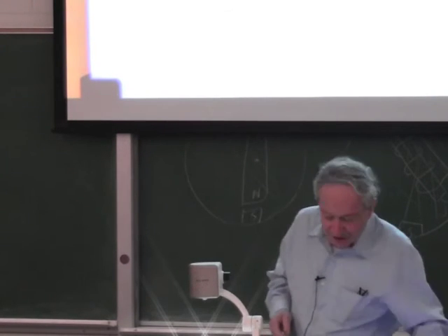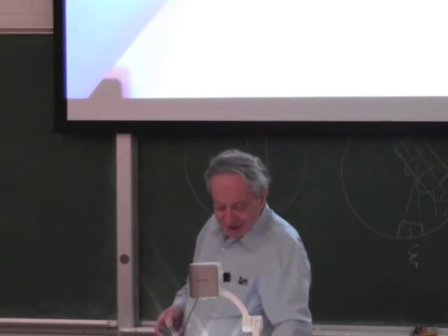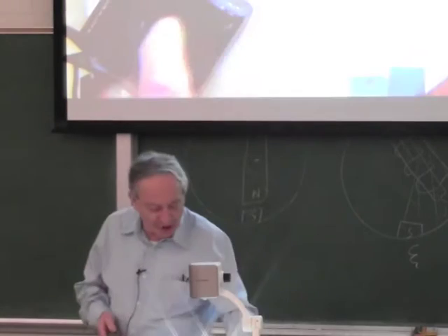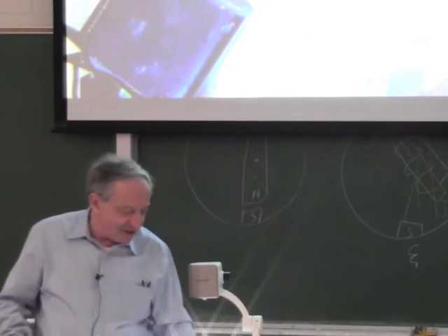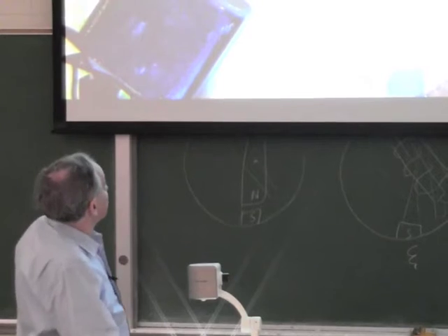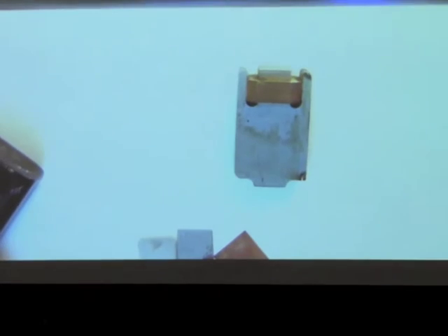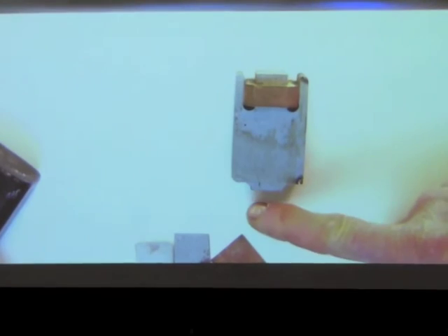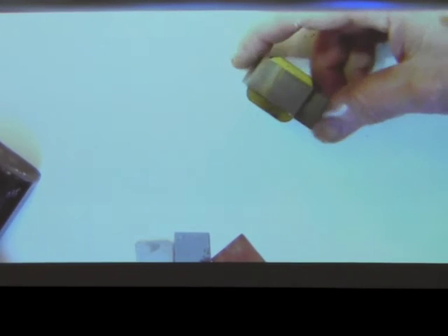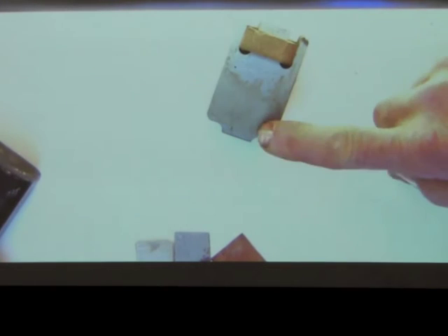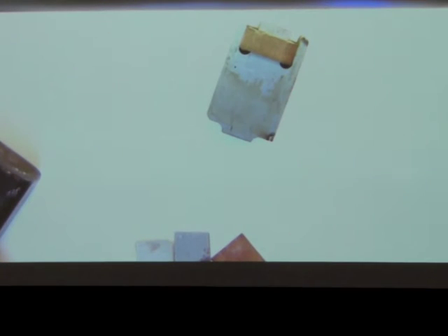If you open this coil, you find out that inside the core of this coil looks like this. That's what's inside. So one side of it, which attracts normally, is just a laminated steel core. That's a laminated core. You can't see the laminations. Maybe here you can even see it's laminated. So one side is a regular laminated core. It's laminated because it runs on AC, right? So everything running on AC has to be laminated.